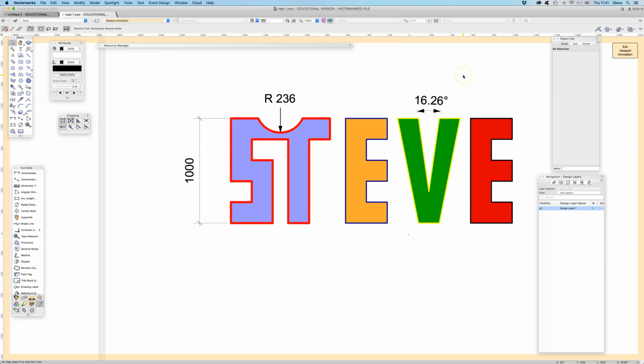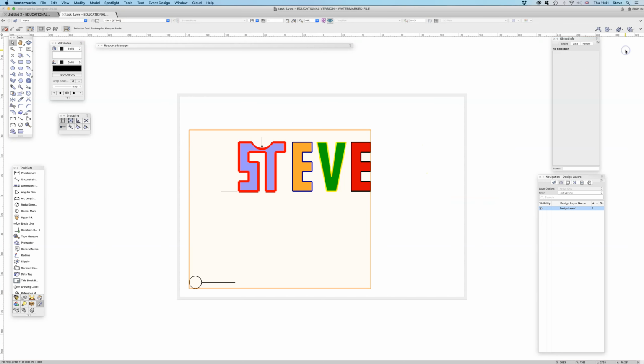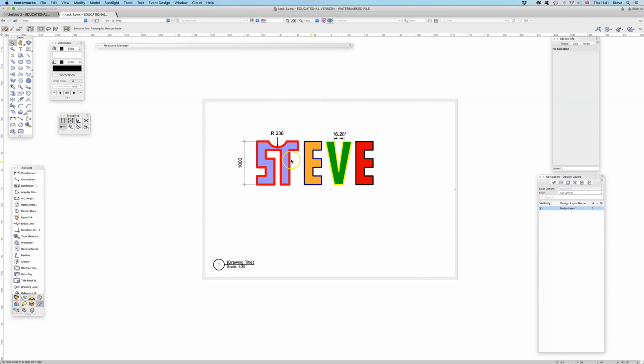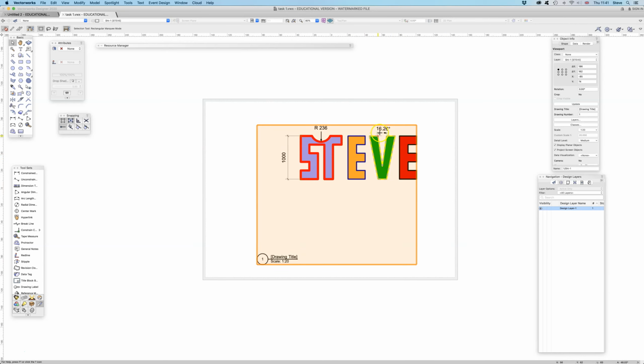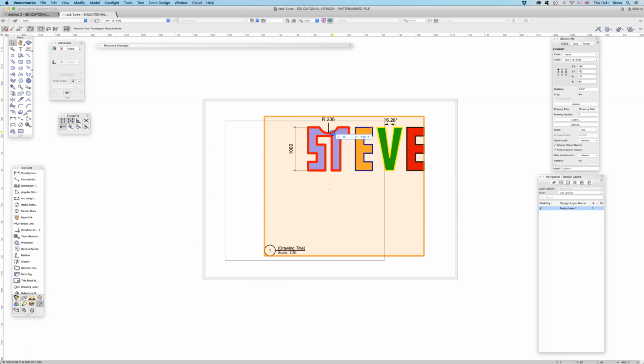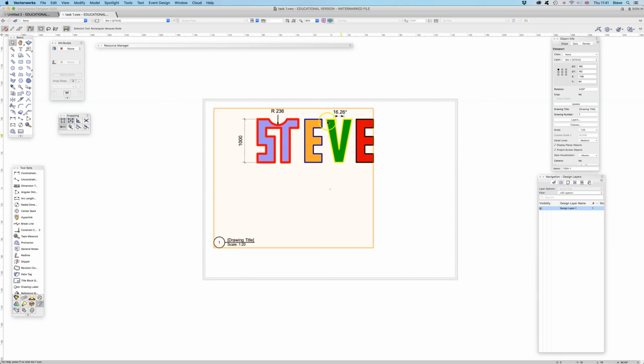But yeah. So what I want you to do is, once you finish dimensioning, exit the viewport annotations, and then you'll be placed back into your sheet layer again. And because the dimensions are within the viewport, it doesn't matter where you put the viewport. The dimensions will be inside it, if you like.